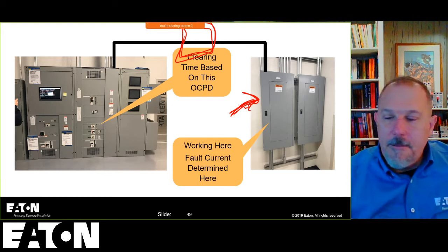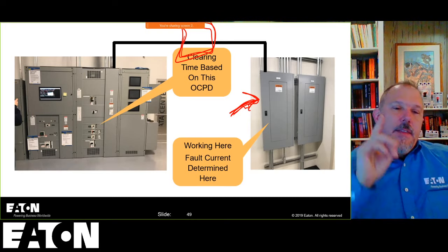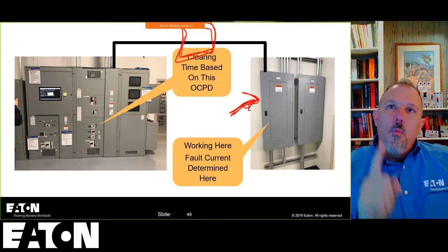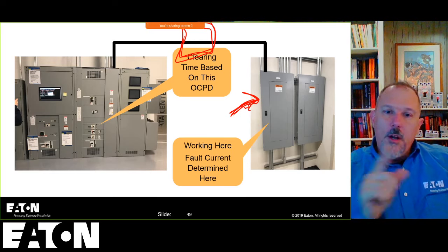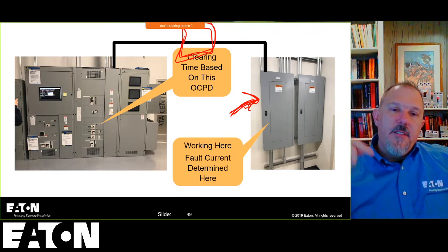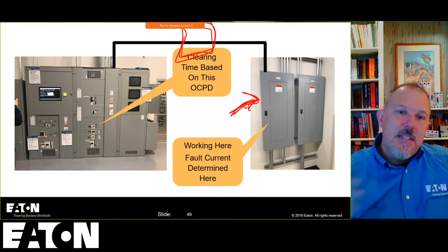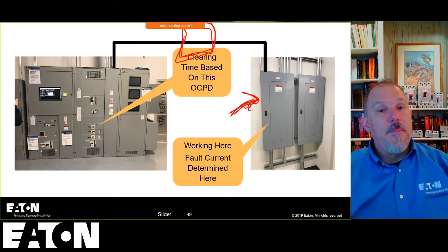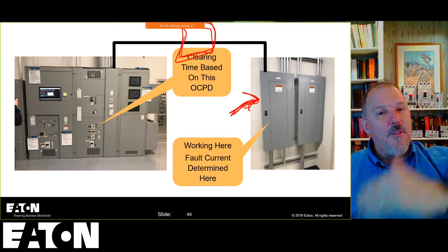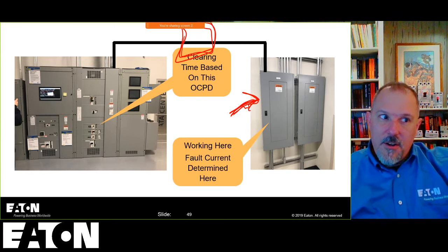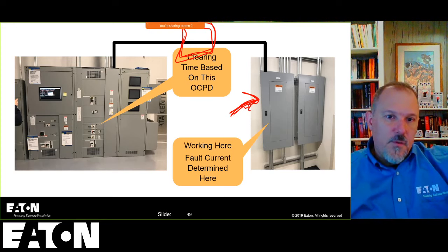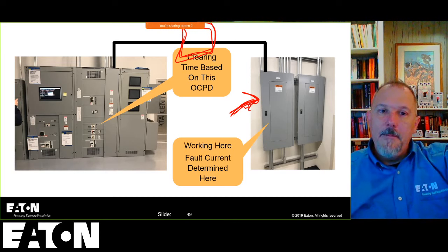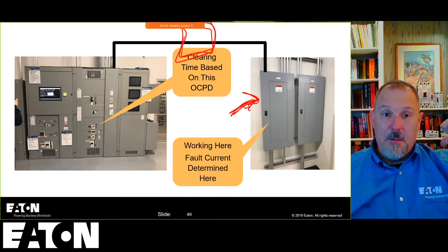And he commented to me that they use a lot of one-to-one transformers, isolation transformers. And they use that because they have a lot of drives and those types of loads, so they want to isolate that power flow. And because you've added that transformer, that primary device, because of the inrush, is going to be greater than what you would have on the secondary. So if it was a normal 600 amp run, I put a one-to-one transformer in there. That means I've got 600 amps of full load amps there that I can still supply. The primary breaker can't be 600 amps anymore.